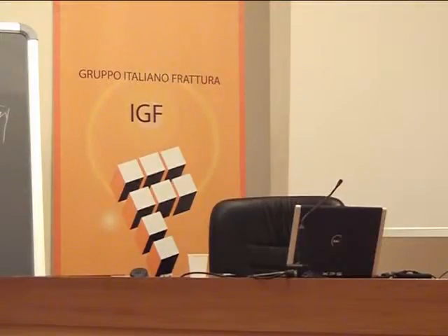I think it's lunchtime. So we redo the a-over-N curve for various delta sigmas. We can determine a kind of S-N curve, and if we take a more sophisticated equation, the NASGRO equation that I showed prior to the break, then we can even start with the threshold value, and we can determine the S-N curve, including the endurance limit. This is what the Norwegians have done many years ago for offshore platforms.